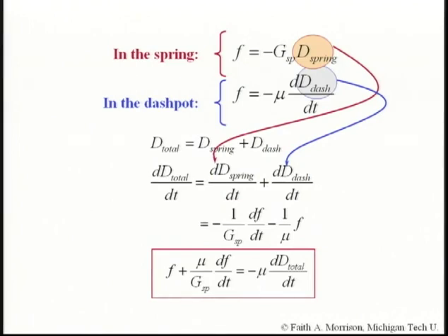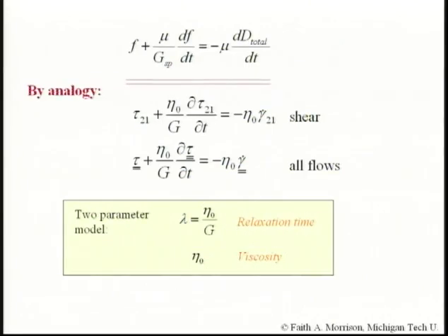What I did here was calculate the total displacement in terms of the rate of change of the force. That became rate of change because we needed to take the time derivative of this elastic term, and then the force itself, because that comes directly from the time derivative here. And we get this differential equation. So here's the final differential equation. It's a very simple differential equation.